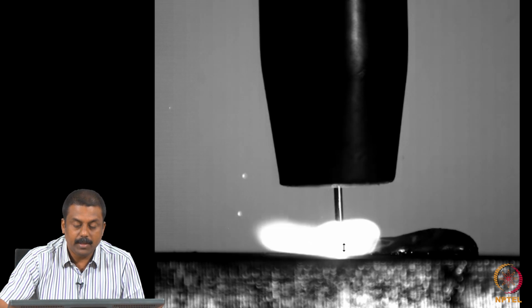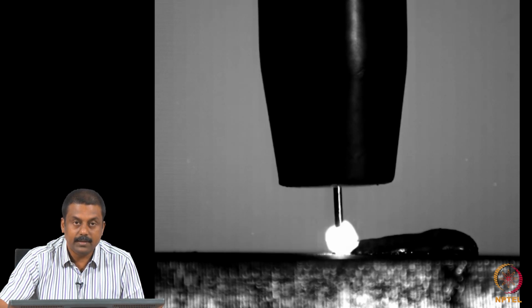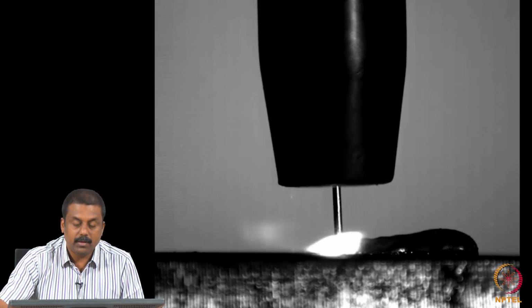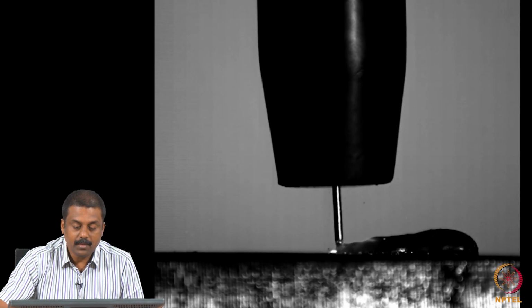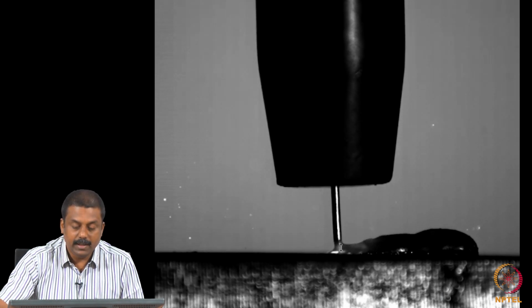And then the droplet is transferred by the forces, by slightly increasing the current as well as the surface tension, when the droplet is retracted from the pool towards the contact tip. So if you look at it very carefully here, when the droplet is actually transferred to the workpiece, the arc is completely extinguished, and the droplet is transferred by the surface tension of the pool as well as the slight increasing current driven by the waveform.